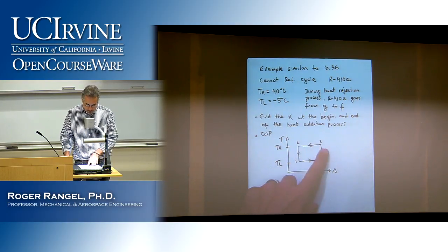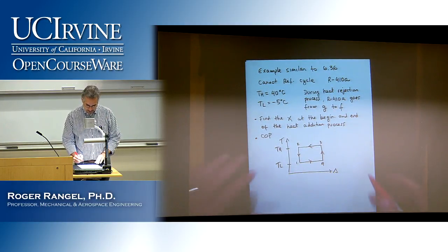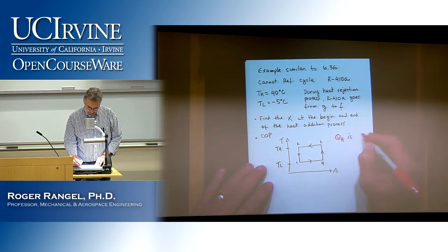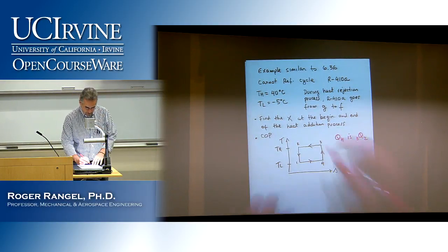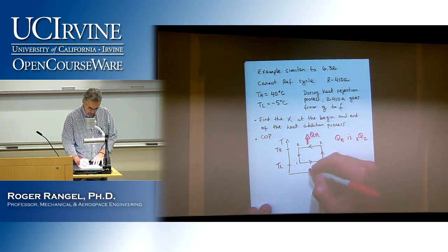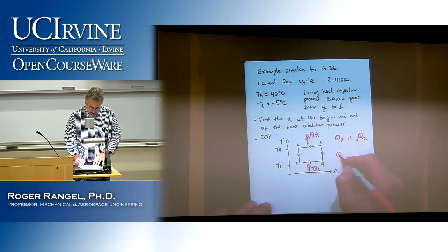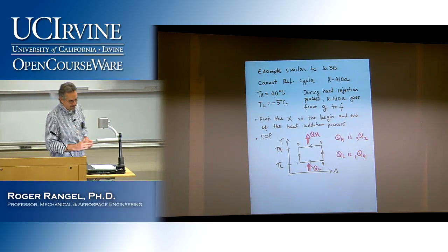So that means that when you go from 3 to 2, that's where you actually have the heat rejection, right? So you can write here Q sub H is Q3,2, right? That's when you take the heat away. And down here, of course, is where you add the heat, Q sub L. So Q sub L is Q1,4. All right? So we have to establish that fact.